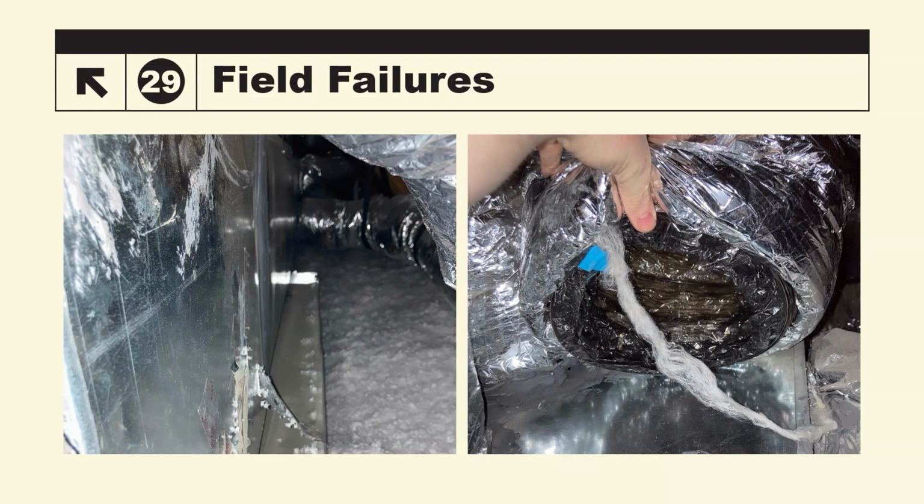And then Guadalupe says, "I believe in some applications, the electrical wire may need to be different. At least it's true on the commercial side." Yeah. And the reason I bring it up again, I'm not sure how they do residential, but the outer jacket of that electrical wiring, unless it's a newer style wire, if it burns, melts, or gets super hot and starts to smoke, gives off contamination. It's a really bad gas that can get into the duct system. So it's not ever a good idea to have electrical wiring in or through a return box or a supply.